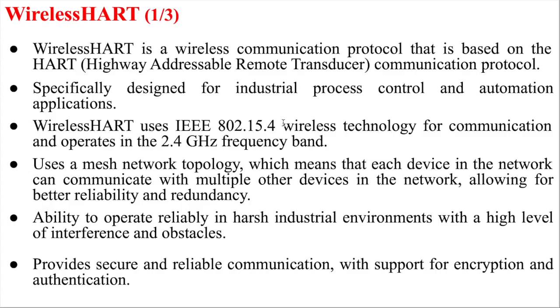Wireless HART is another protocol which is also based on 802.15.4, and the beauty of this one is that it is very lightweight and reliable. That also means the protocol is secure because they use encryption and other things. It is a wireless communication protocol based on the Highway Addressable Remote Transducer protocol. They use it for wireless, though they also support other types of communication medium.